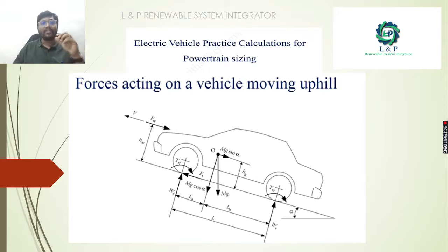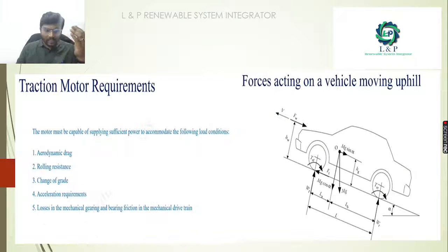If you want to do the practical calculation for powertrain sizing, first try to consider your vehicle is moving uphill. When it is moving uphill, you need to take all these parameters into consideration, because we need to know the acceleration due to gravity, at what force it is moving upward, and what will be the change of grade.